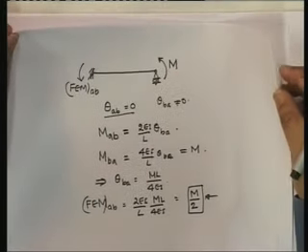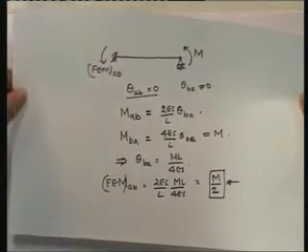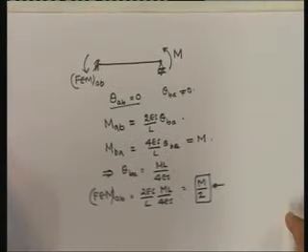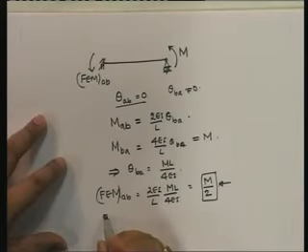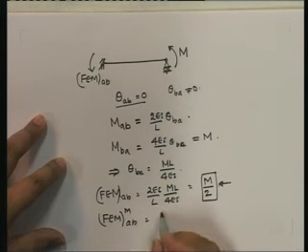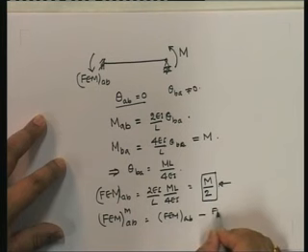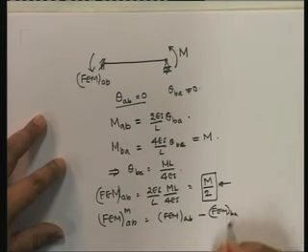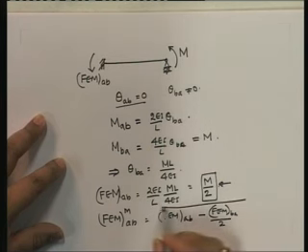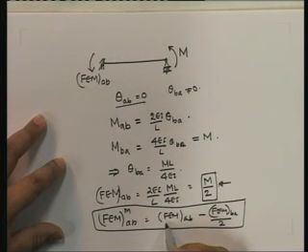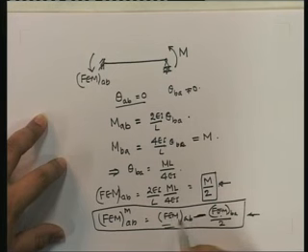That makes it ultimately that the modified fixed end moment at AB is equal to the fixed end moment on AB due to the fixed condition minus fixed end moment at BA upon 2, where these are obtained using the fixed condition. We know how to obtain this.